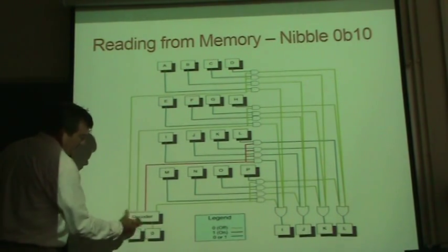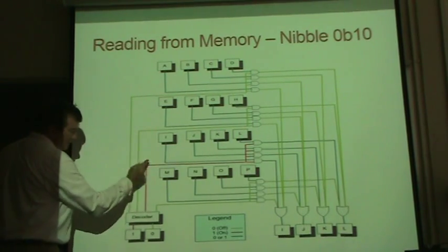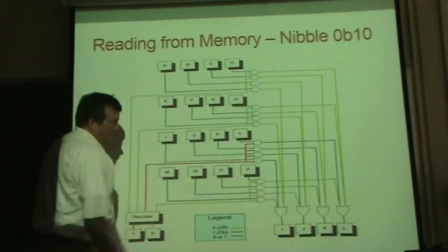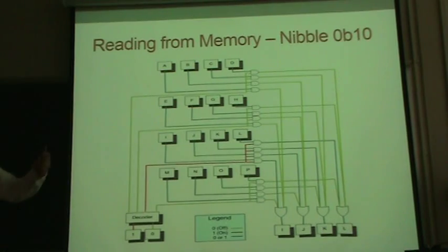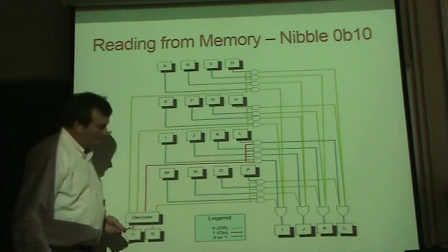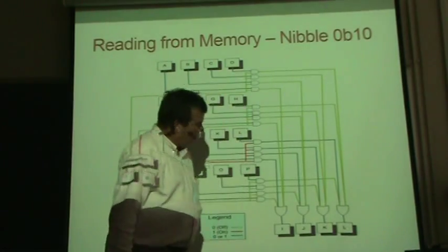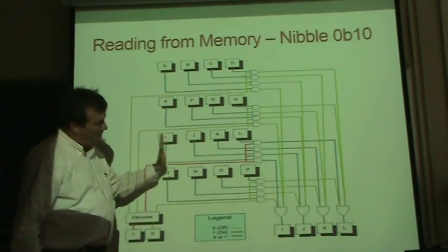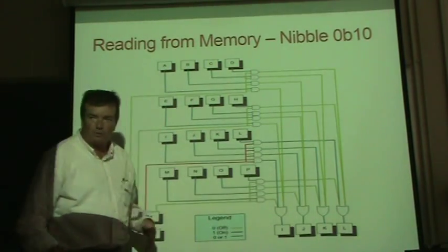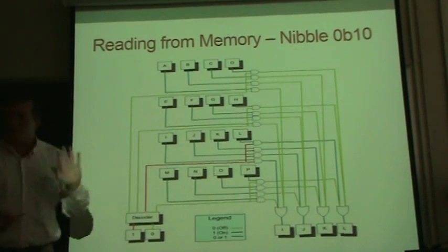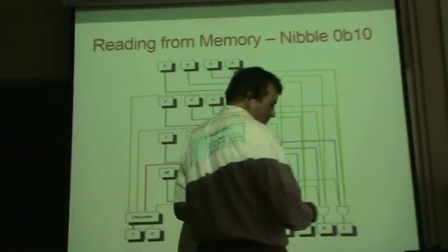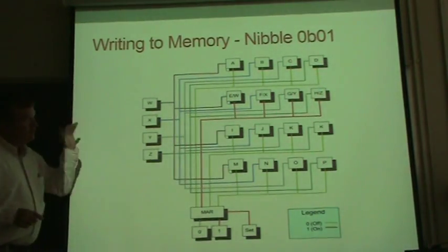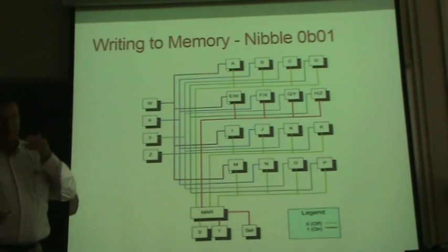This line is on, this line is off, the decoder turns this line on and shuts the other 3 off. And then the values of I, J, K, and L go running into the destination, the 4 destination pieces of memory. So we're going to use the expression memory when we're talking about where you're storing stuff. And if you have a destination, this is going to be closer to the processor. We'll call that set of bits a register, a place where we're going to store stuff to do some basic mathematics.